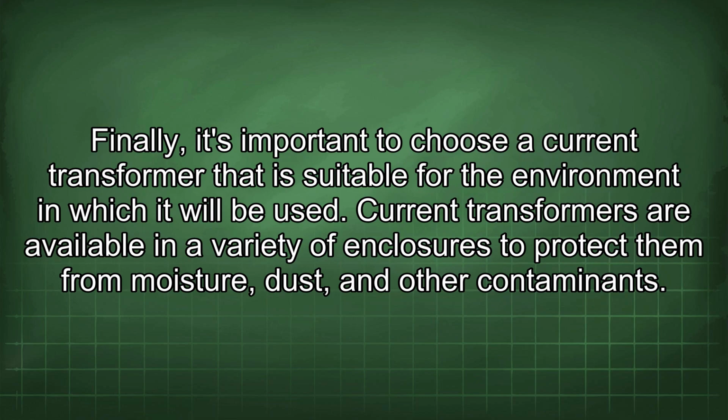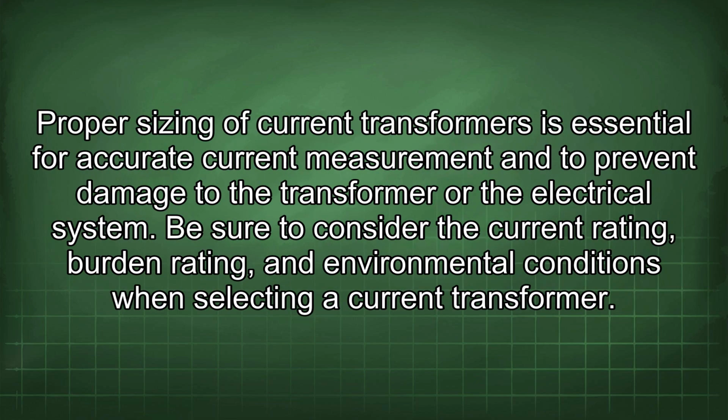Finally, it's important to choose a current transformer that is suitable for the environment in which it will be used. Current transformers are available in a variety of enclosures to protect them from moisture, dust, and other contaminants. Proper sizing of current transformers is essential for accurate current measurement and to prevent damage to the transformer or the electrical system. Be sure to consider the current rating, burden rating, and environmental conditions when selecting a current transformer.